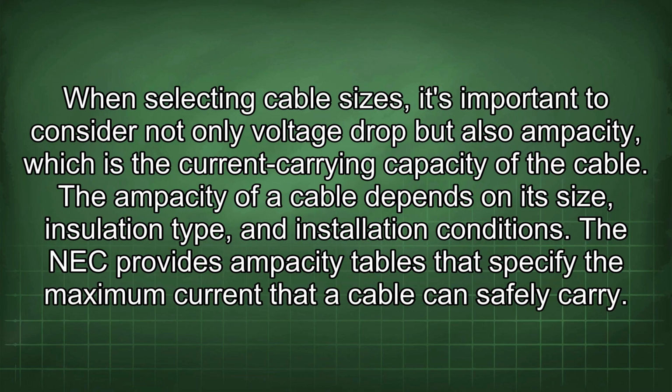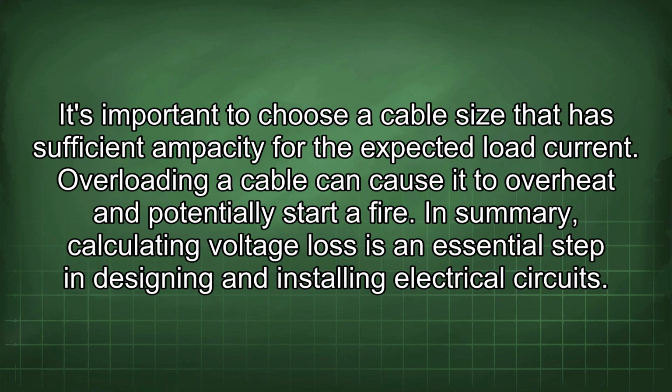When selecting cable sizes, it's important to consider not only voltage drop but also ampacity, which is the current carrying capacity of the cable. The ampacity of a cable depends on its size, insulation type, and installation conditions. The NEC provides ampacity tables that specify the maximum current that a cable can safely carry. It's important to choose a cable size that has sufficient ampacity for the expected load current. Overloading a cable can cause it to overheat and potentially start a fire.